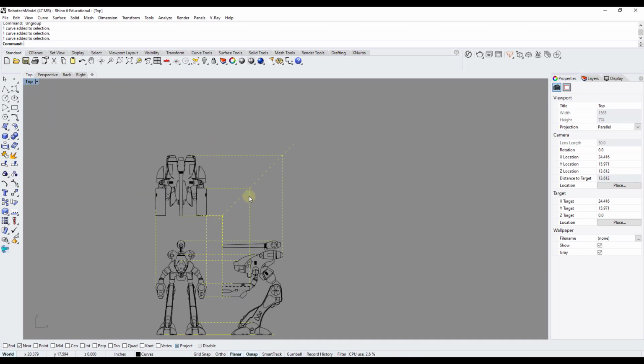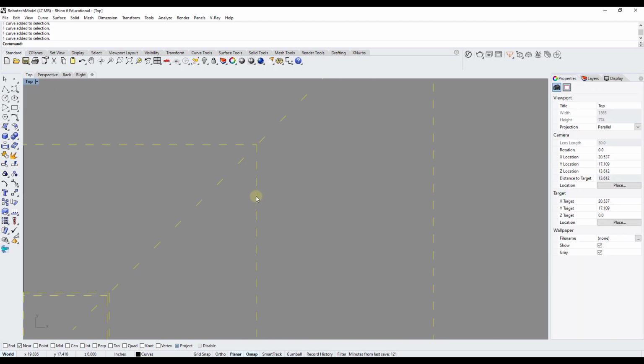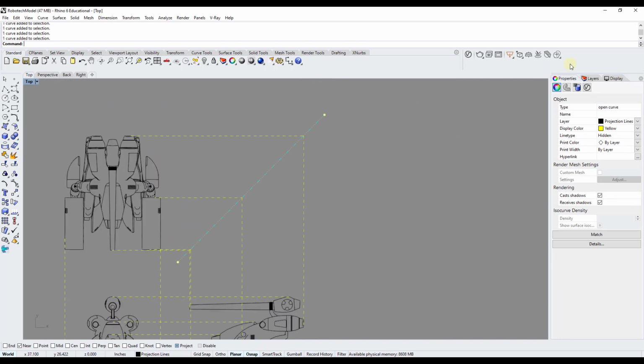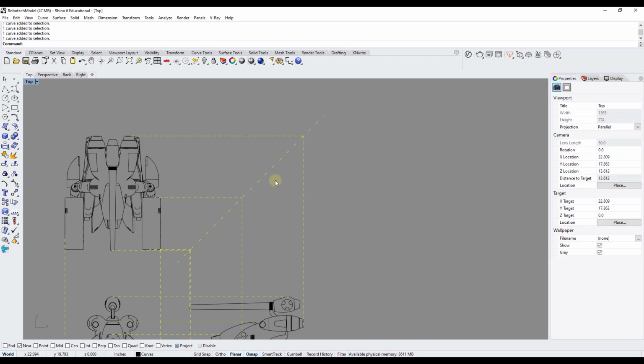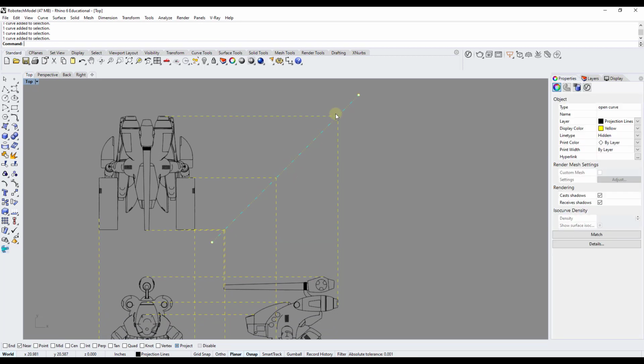So this line here is a bit different from this line. I don't know if you see the difference, but let me select this line, for example. If you go in the properties tab under object, line type, this one is a hidden type of line. This one is hidden. And this line here under line type says dashed. If you want to change the pitch of your lines individually, for example, this is a hidden type of line, so it's a different type of dashed line.